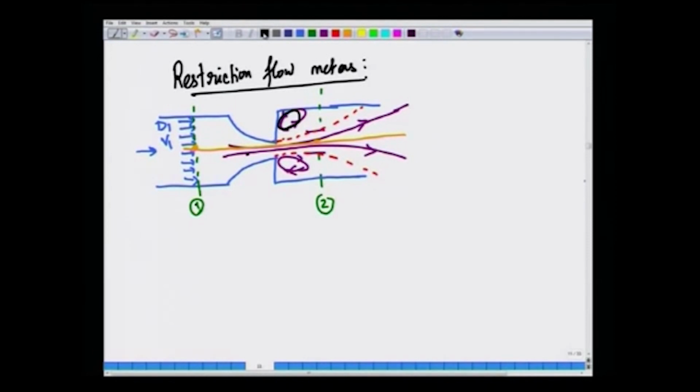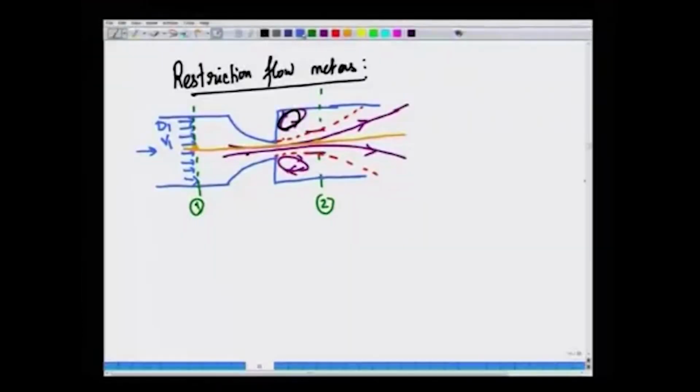Okay. So, this is admittedly an approximation. We will correct for this approximation later, because remember that the Bernoulli equation is valid for a hypothetical inviscid fluid, while no real fluid is inviscid, that is, no real fluid has 0 viscosity. So, there will be losses. Now, losses are neglected to begin with, and they will be corrected for later using an approximate method. Okay. So, this is one of the simplest illustrations of the application of integral energy balances, or integral balances in general.